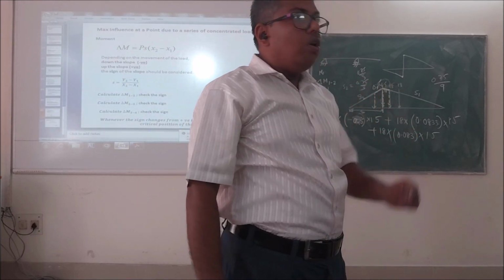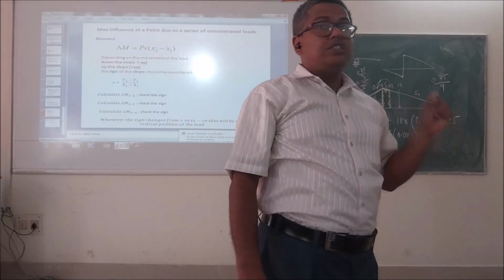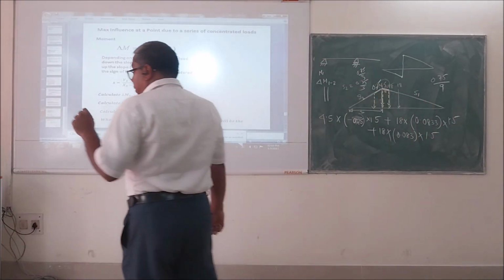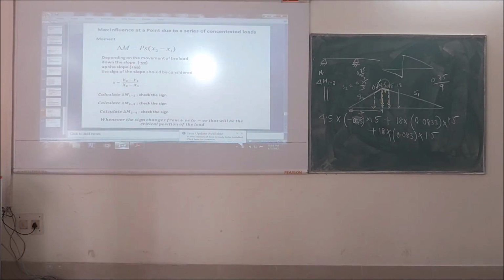Any time you want to find out the maximum influence, either for shear or bending or slope or deflection, whatever it may be, use the change in slope method.